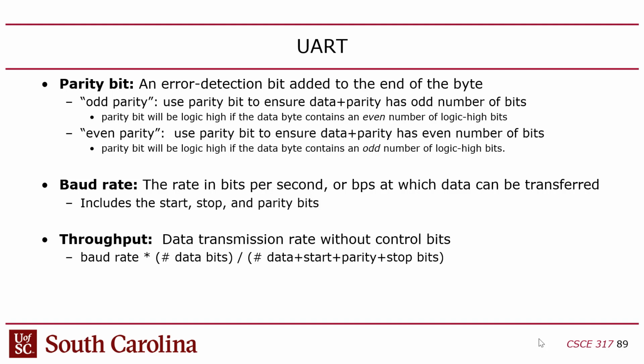And I think I just confirmed for myself that the number of start bits is always 1. The number of stop bits can be more than 1, although usually it's only 1. The number of data bits is 8, and there's often no parity. But technically you could change those settings, though both sides of the connection would have to be set up properly for communication to take place.